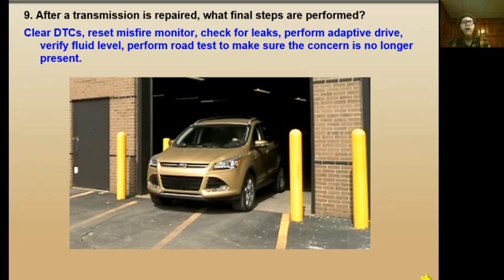It also can figure out things like how much power the engine puts out at these different throttle angles. It'll even learn things to the effect of the throttle body starting to gum up a little bit. That's going to affect the torque being produced by the engine at a certain APP voltage, which is the accelerator pedal, our main input for driver request and power and economy and all that kind of stuff.